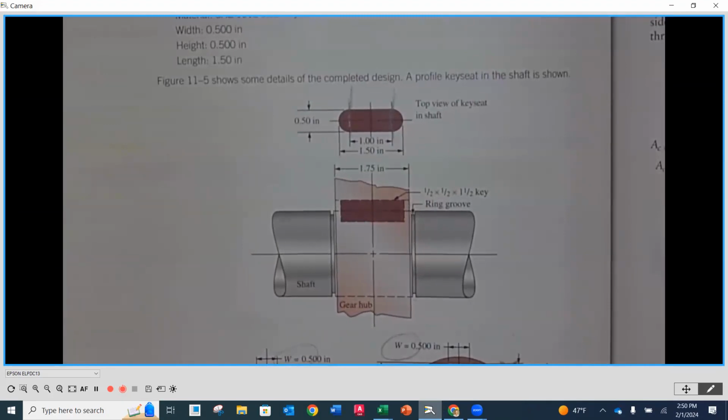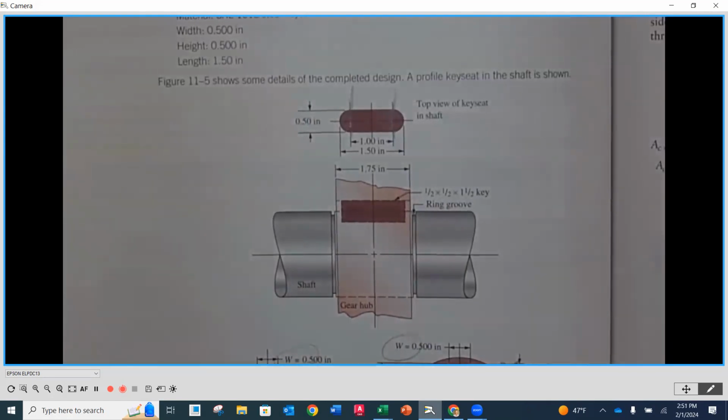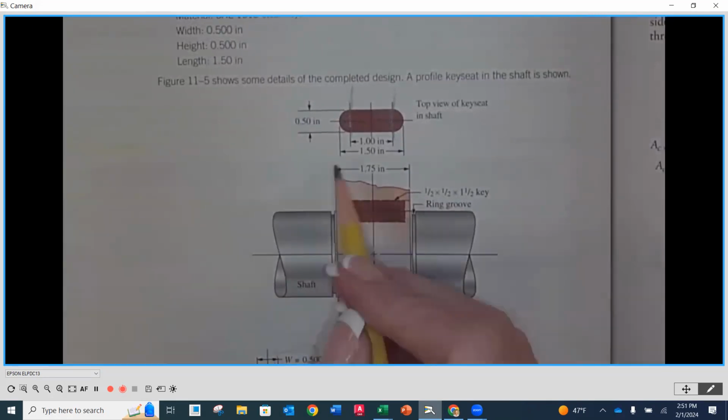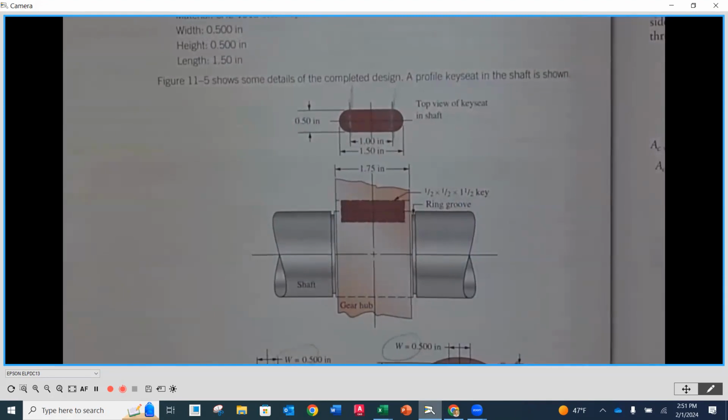Think about manufacturing process, because even making the key with the radiuses, why? That's extra cost that's induced, right? For a part that is designed to fit. I mean, they have keys that are made that size. They're typically called French keys. Yeah, aviation. You can put them in there, but then you have to be hyper aware of the radiuses that you put on there so that you don't hang up on that part.